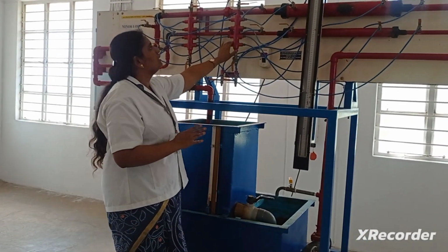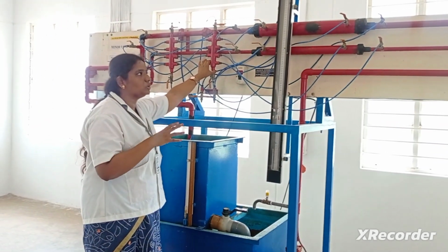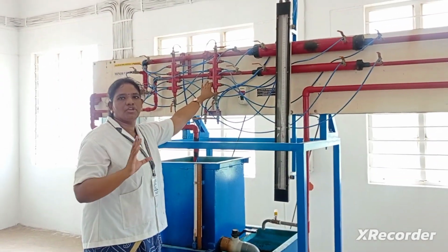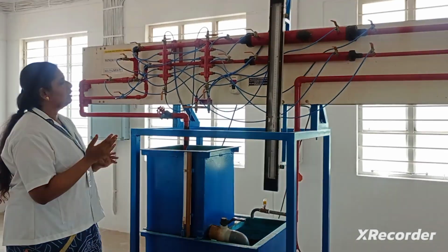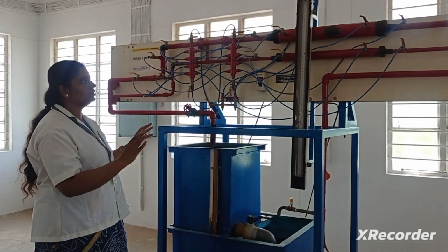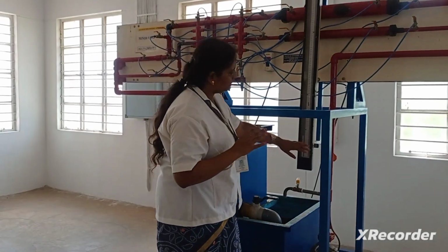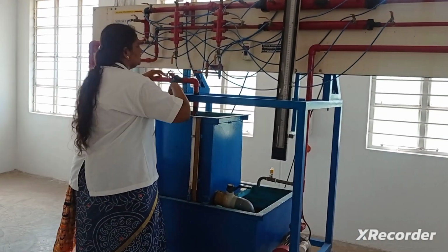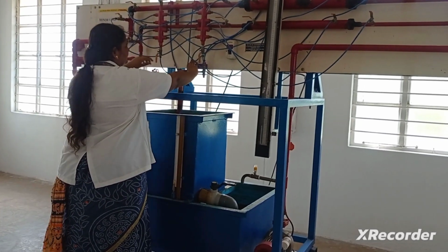How we are fitting here, how we are passing the pressure and how we are reducing the pressure will also affect the discharge through the pipe. Here also we are going to follow the same procedure as we followed before. First we have to level this U-tube manometer using these two valves. Afterwards we can start the experiment.